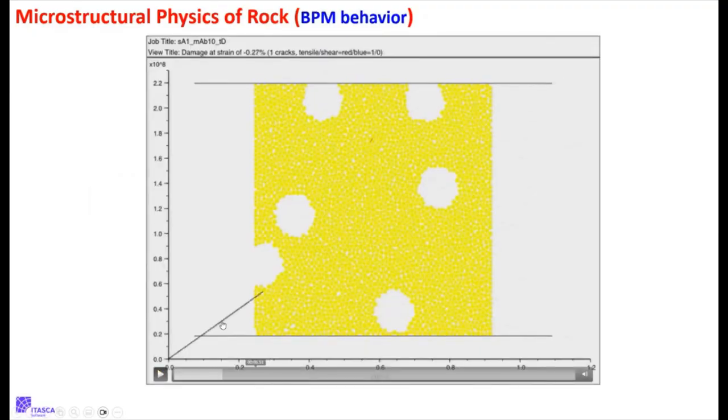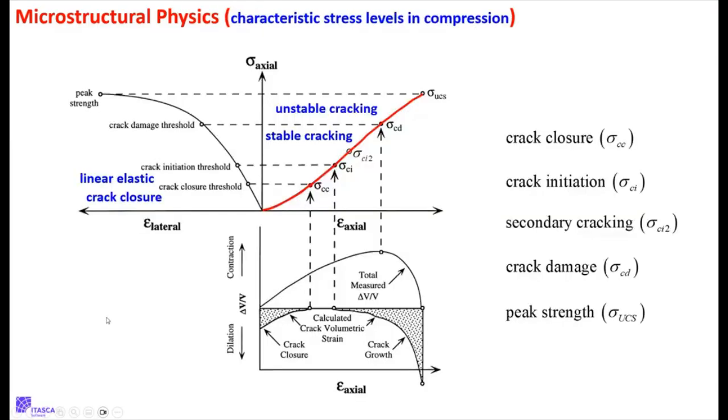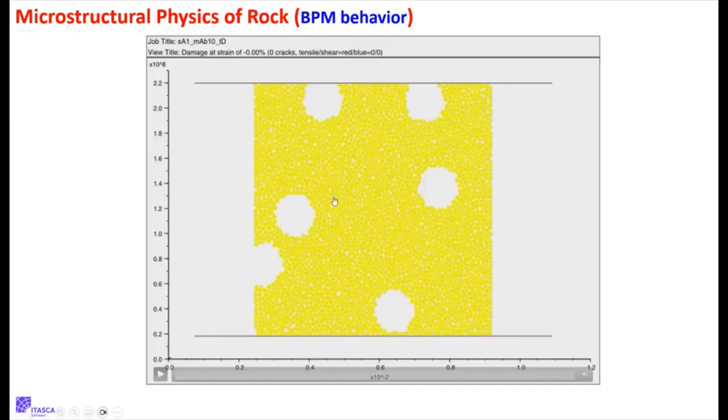So here's the measured stress strain curve. First of all, it's linear. It's not doing this. It's not doing this. And we speculate it's because our initial microstructure was tightly packed and bonded everywhere. And so when we start squeezing it, there are no initial gaps and slits to fill, to start squeezing together. So that's expected. We also expect that if we change the microstructure so that we had initial gaps and slits, we would expect to see that stiffening. So we're not getting the stiffening.